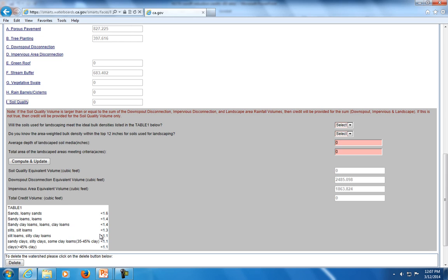So, what happens when we compact the soil, we change that bulk density quite a bit, and we impact the porosity there. So ideal bulk densities are basically bulk densities for different textures of soil that hasn't been compacted or altered. And so that's what we're really looking for. We're having folks look at the type of soil they have and what the bulk density is. So that question we will answer. Let's answer yes for that.